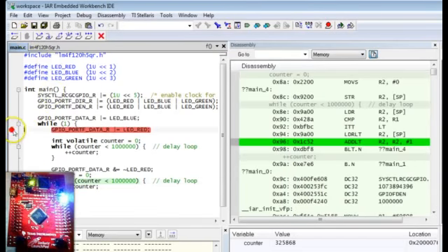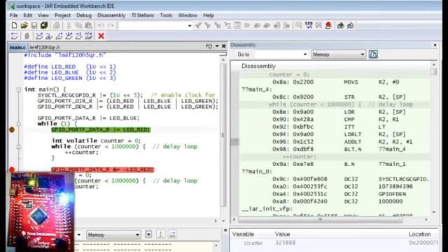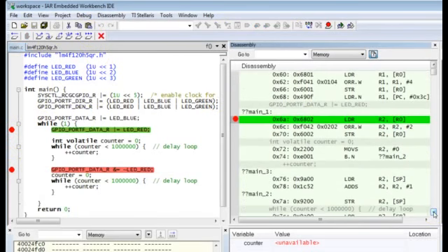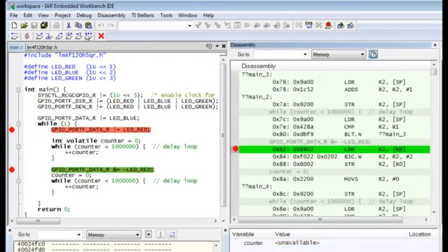Break into the code and set breakpoints at setting and clearing the red LED bit. As you can see, setting of the red LED bit happens as a sequence of load, modify, store operations, whereas the bitwise OR machine instruction is used to modify the data. The clearing of the red LED bit happens as another load-modify-store sequence, whereas interestingly the compiler generated the beautiful code of just one BIC, bit clear instruction, for clearing the bit.